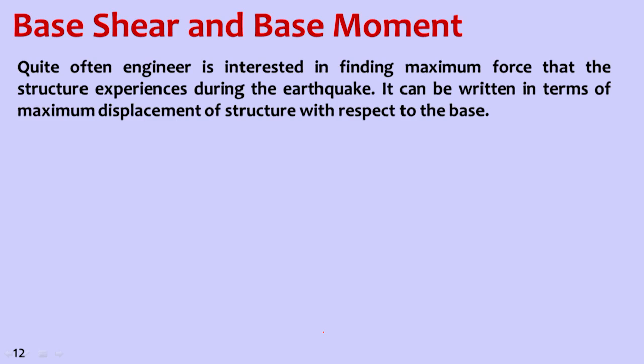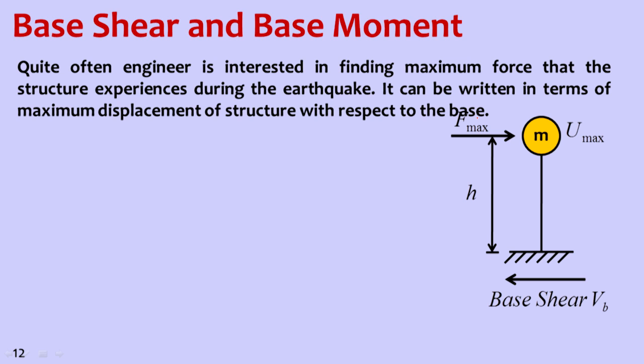Quite often the engineer is interested in finding the maximum force that the structure experiences during an earthquake. It can be written in terms of the maximum displacement of the structure with respect to the base. If you look at this, force is mass into acceleration, and the same force as a reaction here is called base shear. So we can calculate base shear and also base moment, because the force is acting at height h from the base.